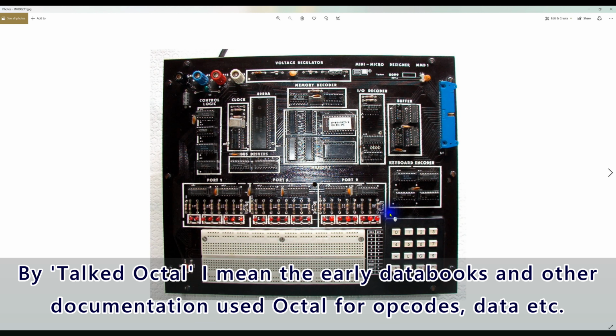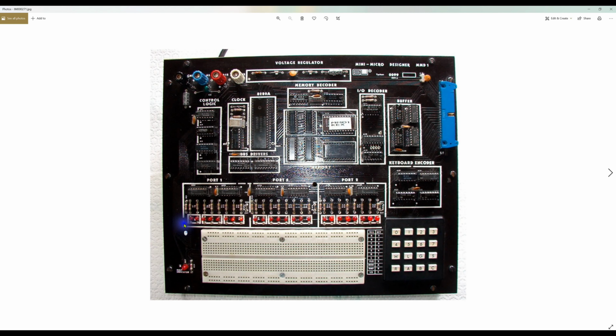And what I mean by that is if we're looking at the address bus being represented here, A0 to A15, and the data bus here, data 0 to data 7, notice that the address bus is broken up into two blocks of 8 bits. So if we were at the absolute top address, where all the address pins were 1, you would read it as 377, 377.